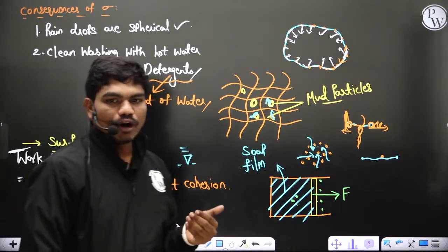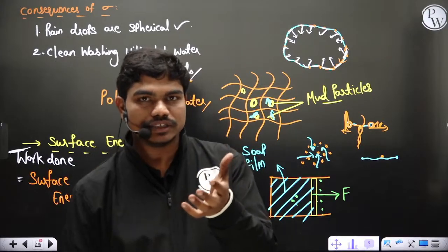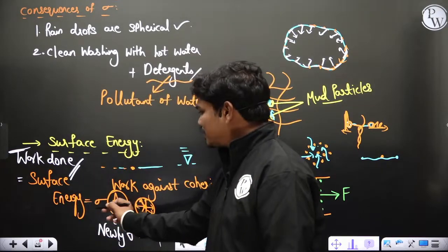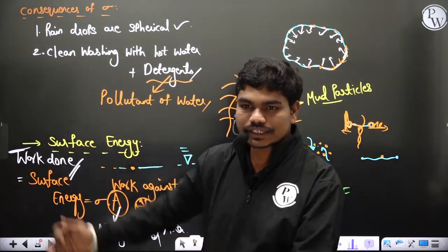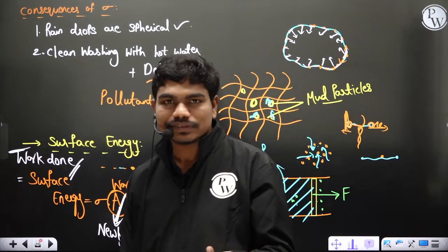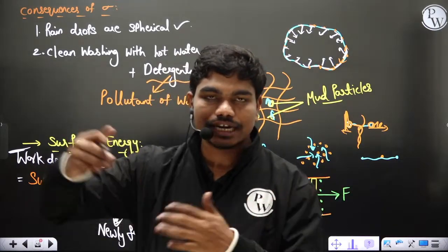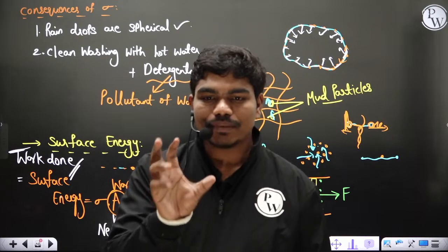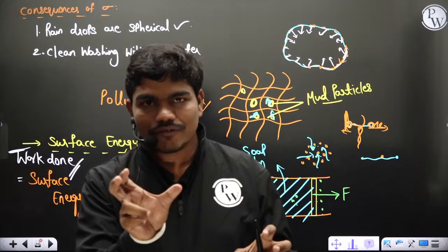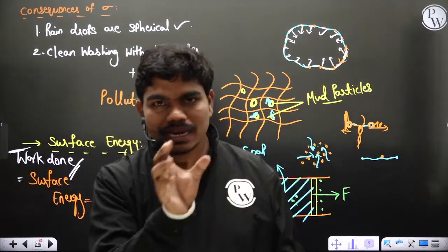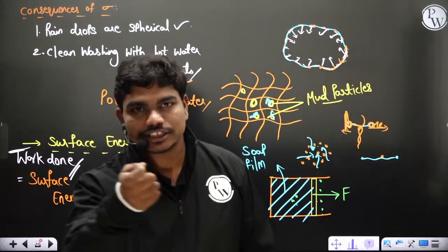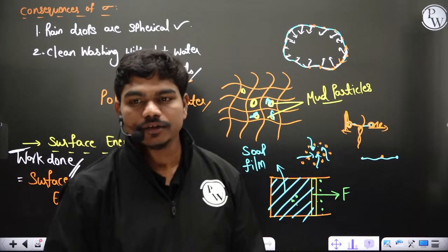Generally, any body, to reach equilibrium, tries to attain minimum energy, or minimum surface area. If this has to be minimum, then once you decide the fluid, sigma is fixed, so A has to come down. For a given volume, the minimum surface area, mathematically, if you do first differentiation and equate it to 0, you will see, suppose I make a cube, a sphere, a cuboid with the same volumes. Out of these three, the minimum surface area will be for the sphere, which also happens conceptually because of localized stretching at each and every point. Clear to all of you?